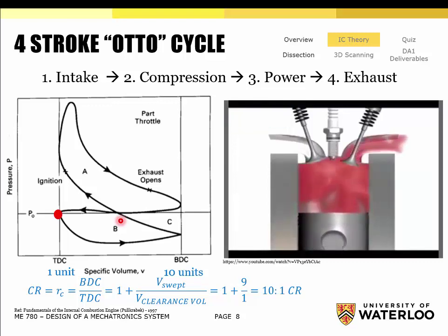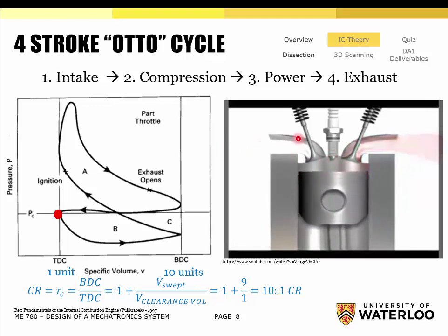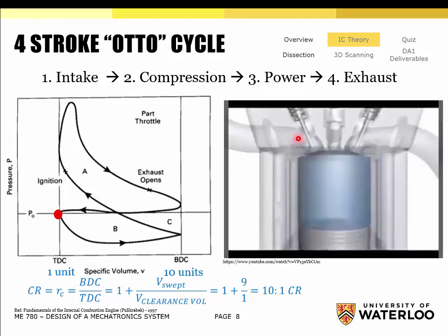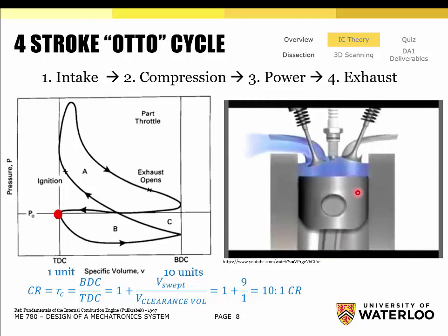First of all, a turbocharger is a device that increases the pressure going into the cylinder. So instead of the air going into here being what's called naturally aspirated, or just drawing in from the natural atmosphere, you're implementing a device that acts as a compressor that pre-compresses the air going into the intake. Okay? So what is that going to do to the pressure inside the cylinder? If you start with a higher pressure, what are you going to end up with? Higher or lower? What do you think? If you start with a higher pressure in the cylinder and you compress it, higher.